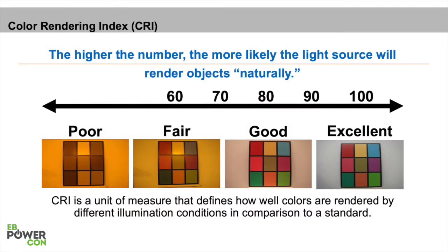So that is kind of like high pressure sodium, or even probably closer to low pressure sodium, which I don't know many places that still use it, but it definitely had a very poor color rendering index. Then you go to high pressure sodium, which is still that orangey light that you see in some neighborhoods. And yeah, you can kind of see what the colors are, but some of them look off. So, you know, for reporting, oh, there's some car sitting on my street for the last 3 nights, and they ask you what color it is.